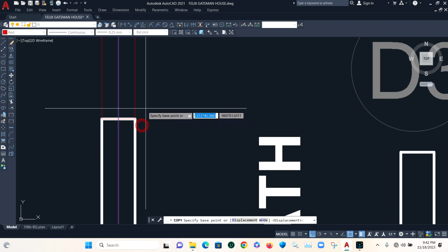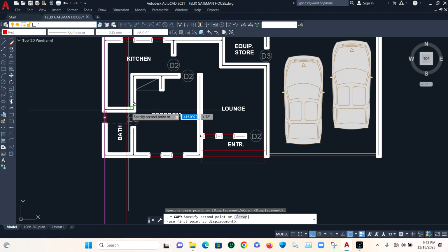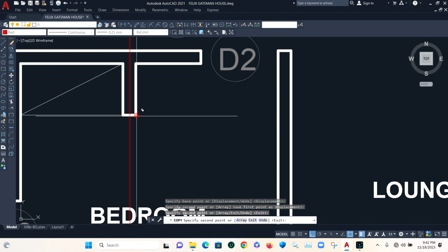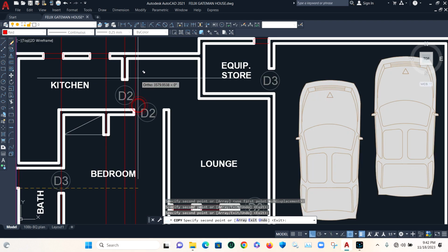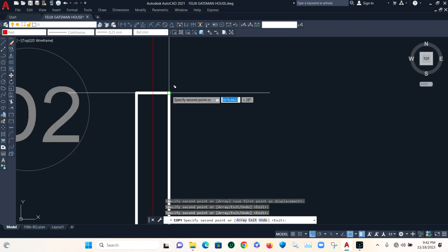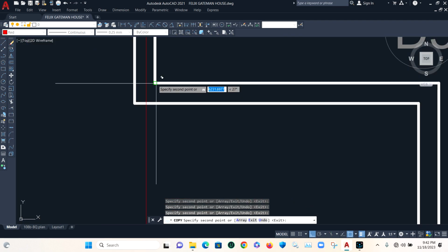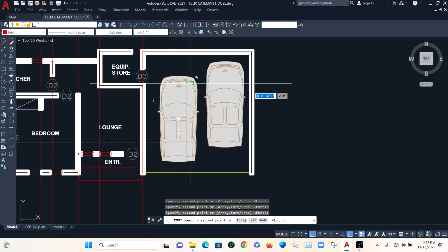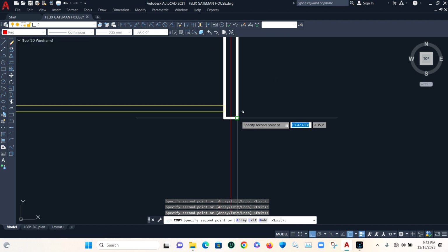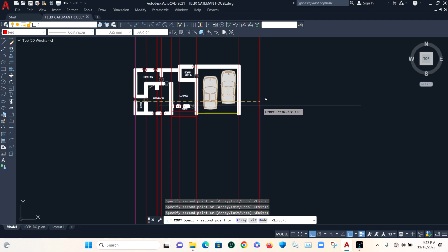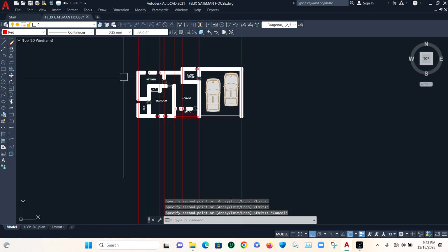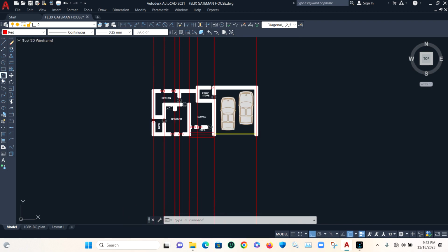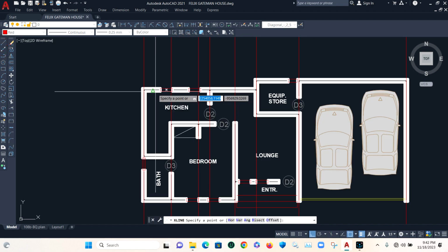Now, I'm gridding, setting the vertical grids for all the walls. I grid every one of the walls. Some might not be useful to me when I finally get inside Orion, but I choose to do all of them at once so that I don't start gridding inside Orion. Now, if you see, we have gridded all the vertical walls here. Now, I'll go over to the horizontal walls.